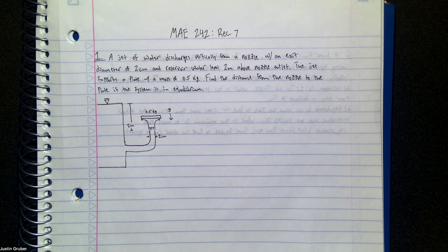But essentially, you take all of your mass, momentum, and energy equations, and you can make assumptions for them: if the flow is steady, inviscid, uniform, incompressible, all that stuff, you get a collection of terms that all add up to a constant value along a streamline in some fluid. So we can use that, and it's really useful for a lot of applications like this.